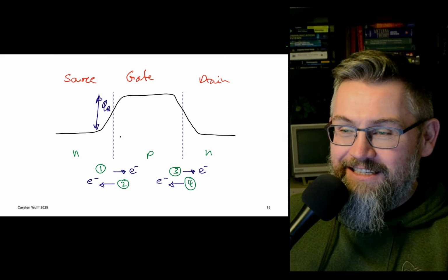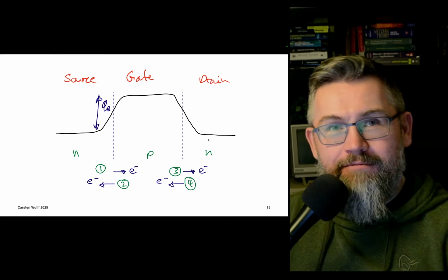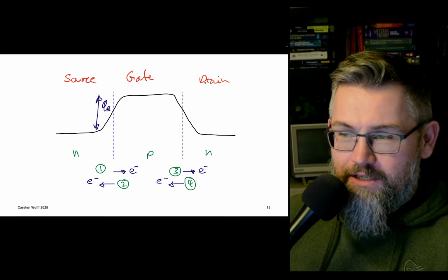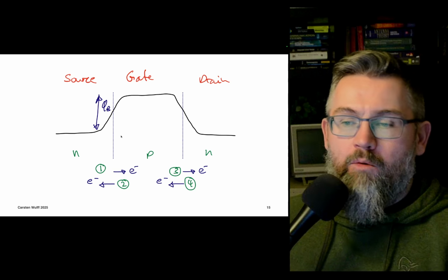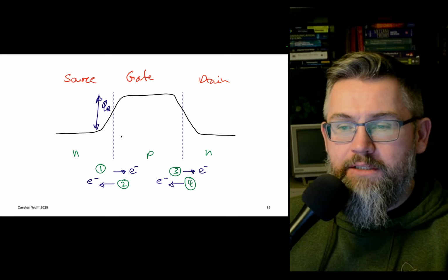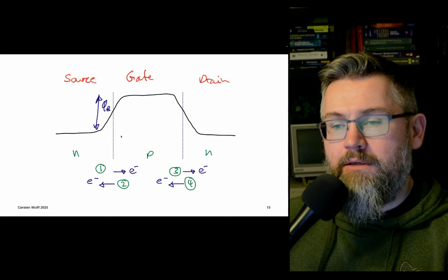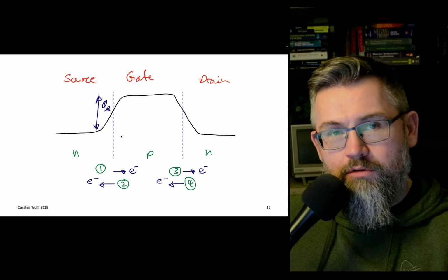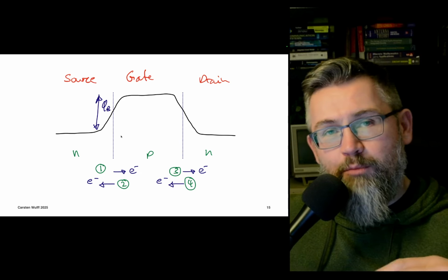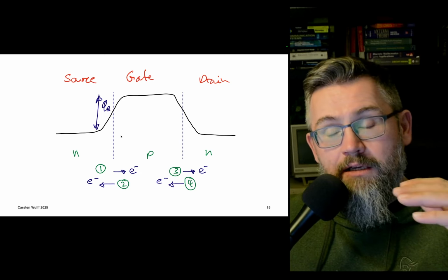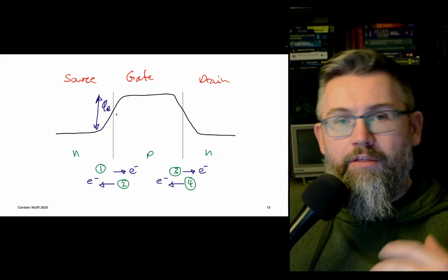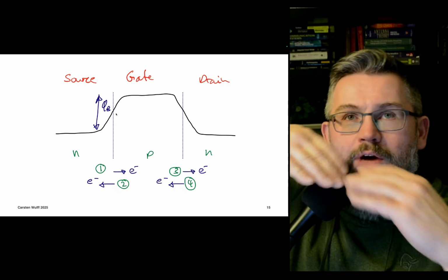And the x-axis, that's just a horizontal line in the x direction. So it's sort of source, gate, drain, same thing. Now, the fact that the carrier concentration and the doping is different here means that there will be bending of the bands. So remember here, when we put p-type silicon together with the n-type silicon, the Fermi levels have to align, which means that the conduction band, which we're looking at here because we're looking at electrons, has to have a bend in it.